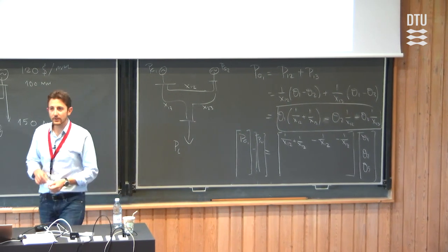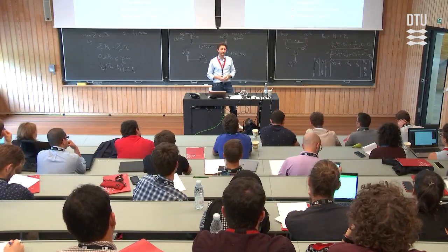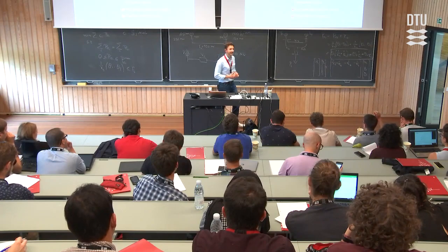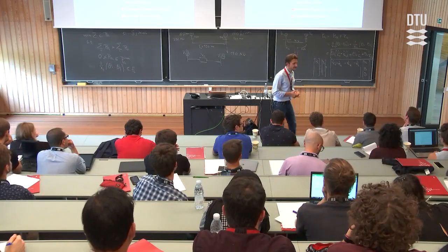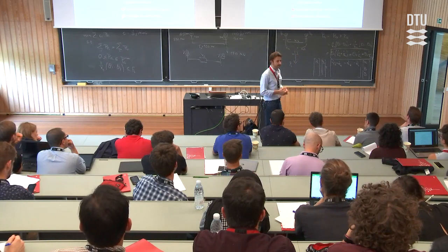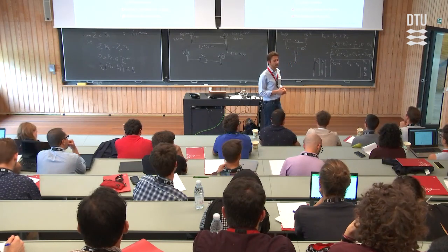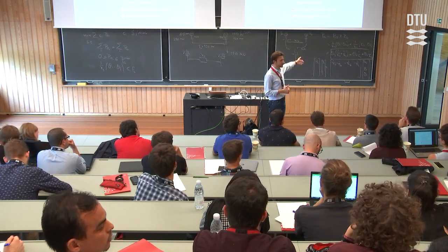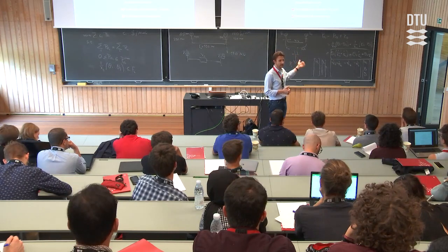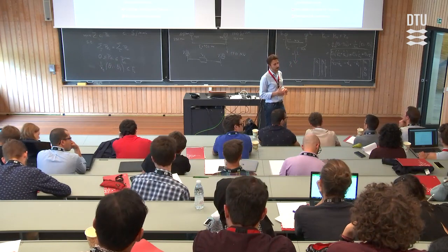Good. Questions? If there are no questions, then there's an exercise. So in your expression, the power are expressed in per unit? Yes. So also the reactance? The reactance is also in per unit, and that's also very important. Since the reactance is in per unit, radians are dimensionless, we need to have power in per unit.